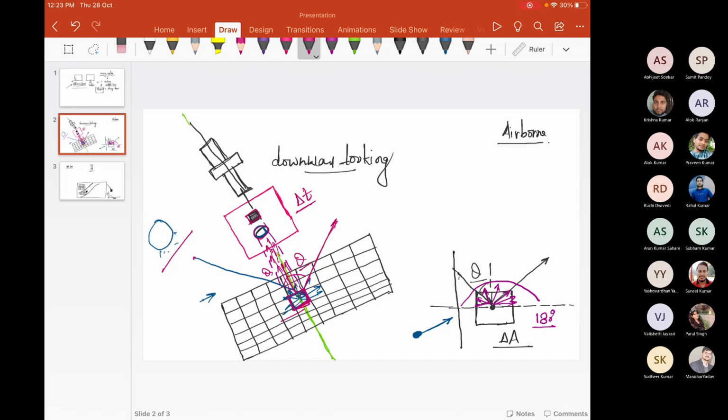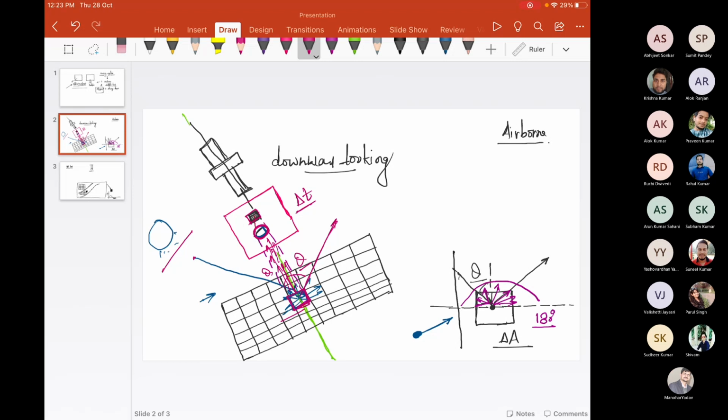So this energy which is in the IFOV of the sensor is collected at the optics over here. Finally, it is confined at its focus. At the focus, we have a detector, and this detector collects the entire energy that is in the FOV, IFOV of this sensor, this optical part over here.